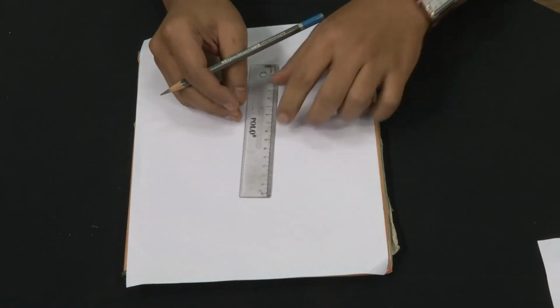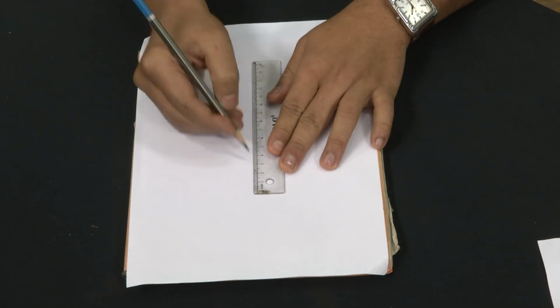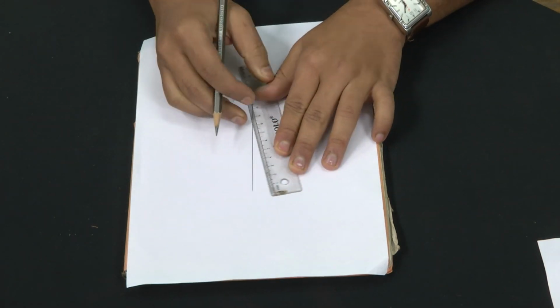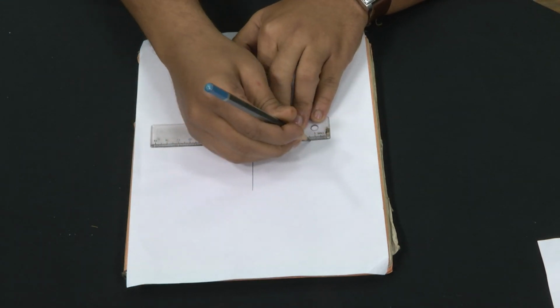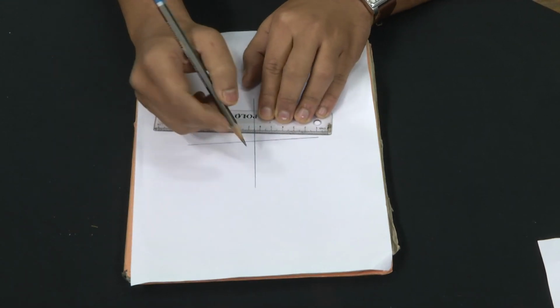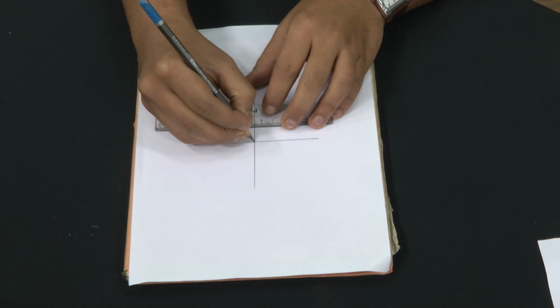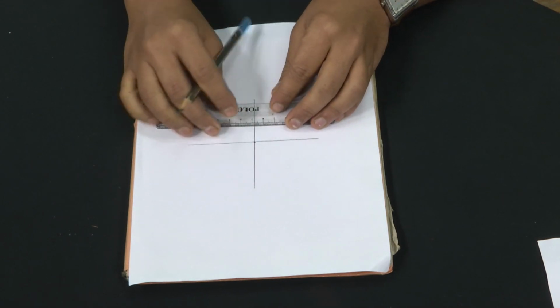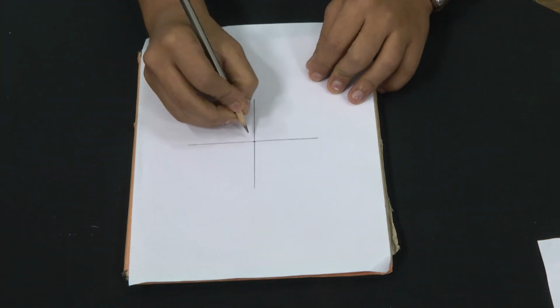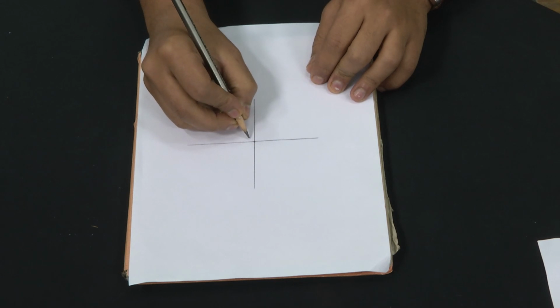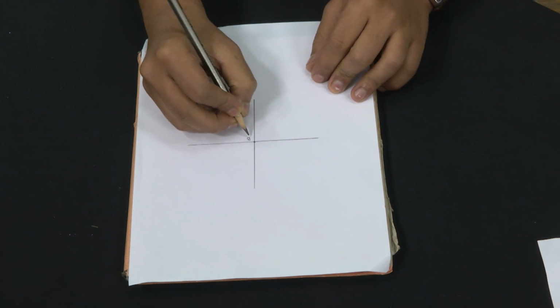So, again for this problem, without the help of stereo net, we will try to find out the orientation of the ore body. So, again in a blank A4 paper, first we draw a biaxial diagram to fix the coordinate system. Now, we plot the spatial disposition of the boreholes. So, first we fix a borehole in the origin. In this problem, we fix the borehole B. Suppose this is the borehole B.